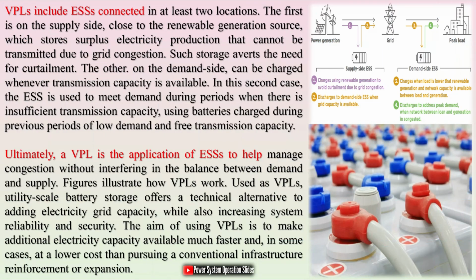How VPLs operate, a high-level flow. Monitoring and state estimation: PMUs and SCADA feed the EMS/DMS, which compute the current state, flows, angle differences and limits. Detection of congestion opportunity: optimization and market signals identify a need to increase transfer between two regions, for example a renewable surge in area A that must reach area B.